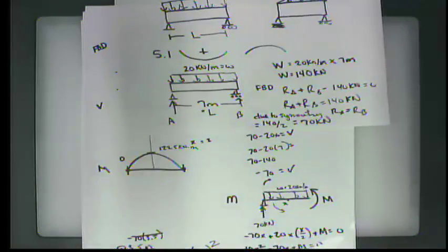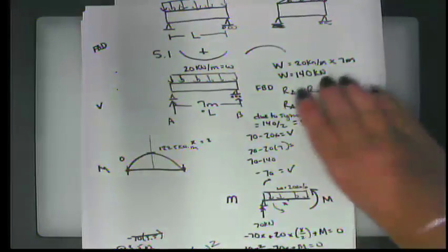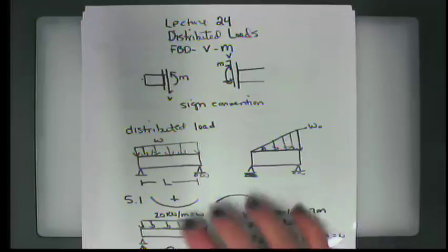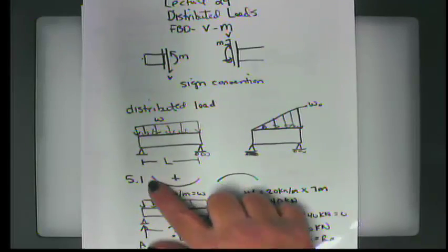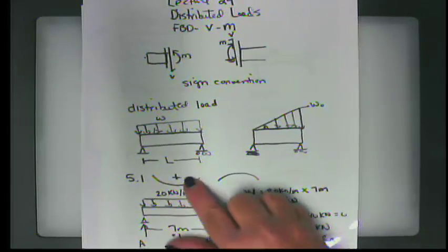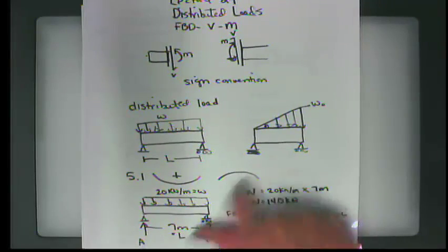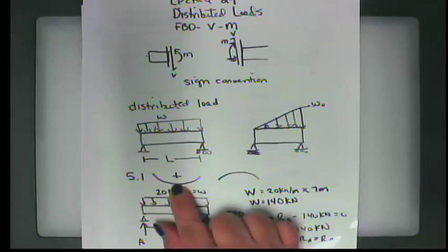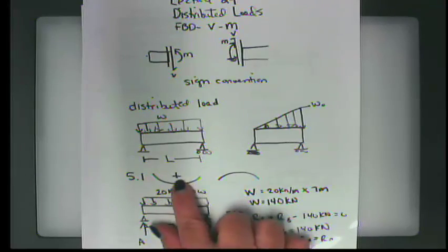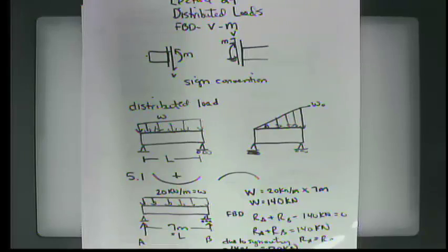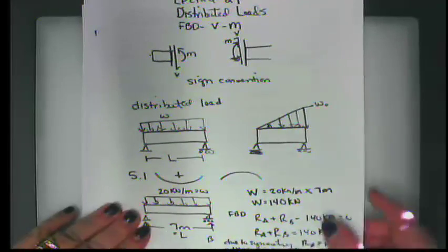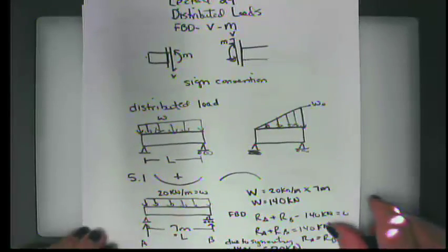Okay? Now, another thing about this is kind of a way to remember this too. I do not know, some people like this, some people do not. But if you can remember the shape of how a beam is bent, as to whether it has a positive bending moment or a negative bending moment, think about this as being like a little smile. Smiles are positive, so you get a positive bending moment if the beam is bent upward in a smiley face. All right, do you guys have any questions about this?